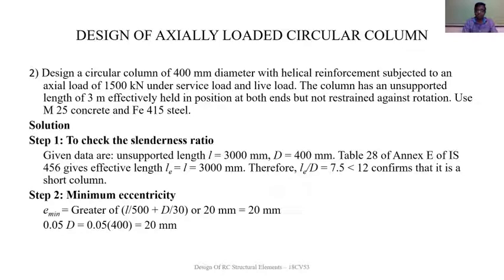Therefore, L effective by D is 7.5, which is less than 12. Hence, the column is a short column.